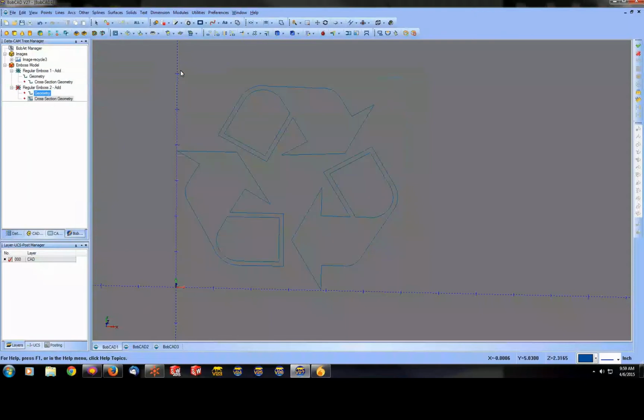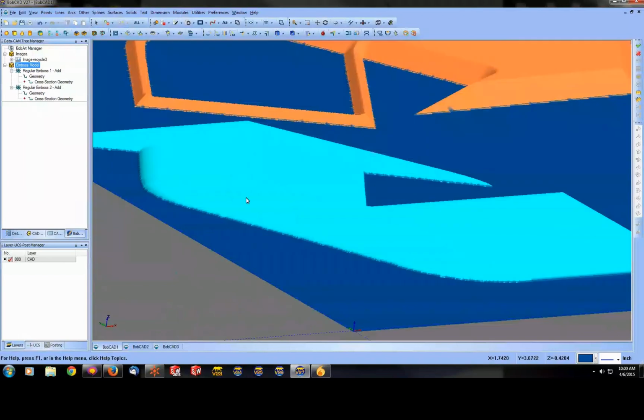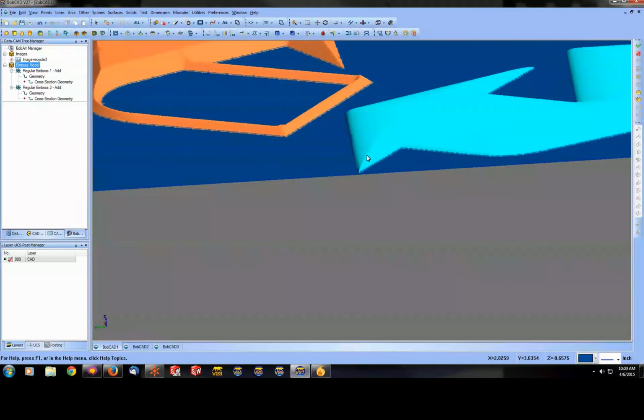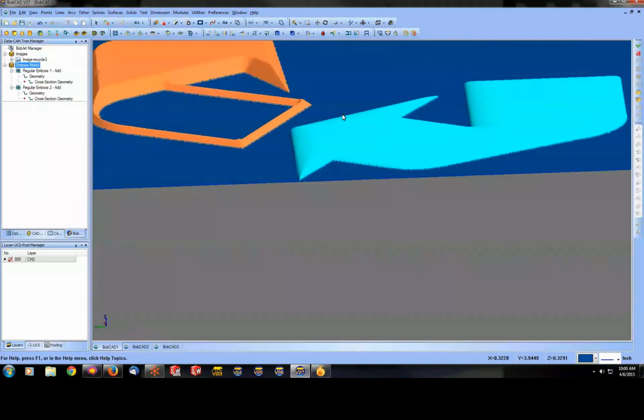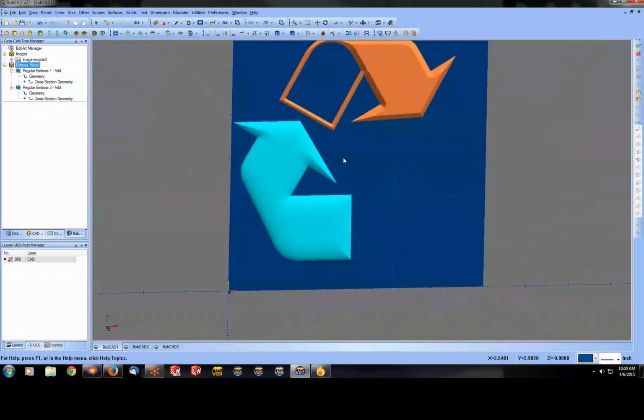Go in and pick our geometry. We can hit the E key on the keyboard to get rid of the embossment that's there. Reselect our geometry, and let's just pick some of that model. We're not going to pick the inside. Right-click OK to verify it, and then if we go to regenerate and bring back our embossment, that gives us a different type of emboss. So it's just a small little radius on there instead of the sharp angles that we have on the other. So depending on what you select, depending on the type of embossment you're doing, changes all of that.